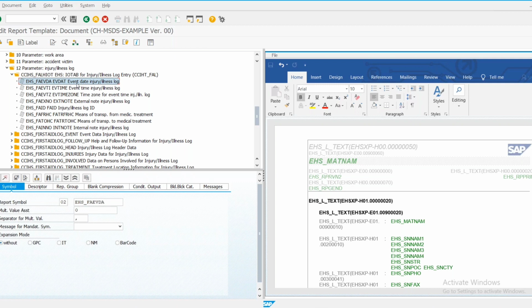First, you have to have an idea about the report template. Then at the appropriate place, you keep the cursor, and when you add those report symbols, they will get added. All the green letters you see on the report template are your report symbols. All the text in green color. That green color text will be replaced by the actual data.